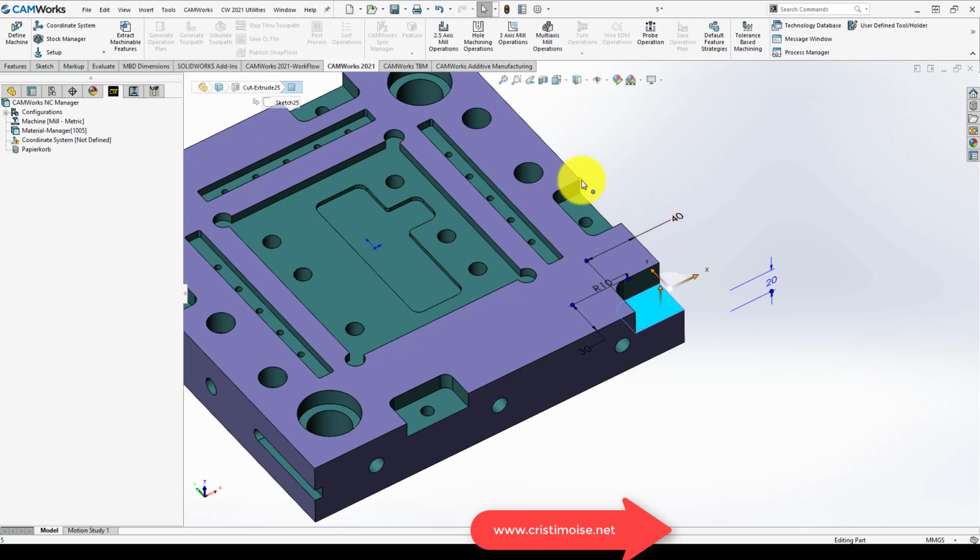So for CAMWorks, when we have a slot missing this empty wall, it's called air segment offset, and this air segment offset setting will help CAMWorks calculate the strategy and use this empty area to engage and retract the tools. Also the same for a corner slot.